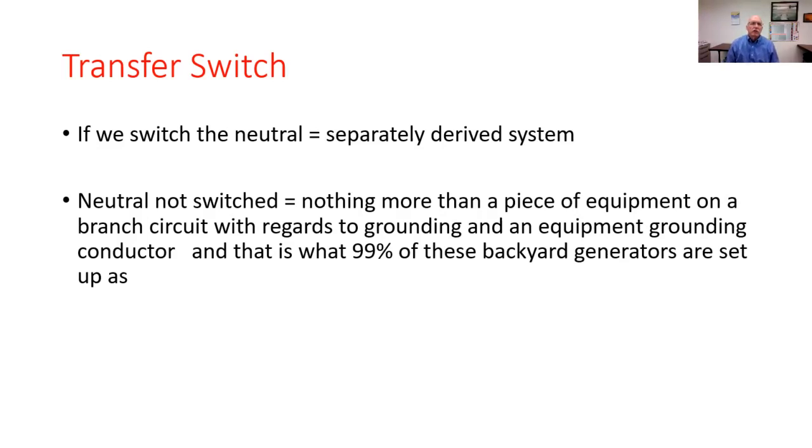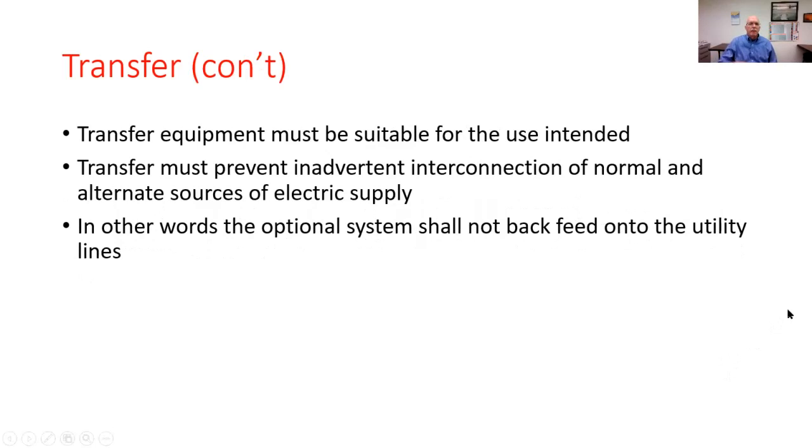And when you don't switch the neutral, it equals nothing more than just a piece of electrical equipment in a branch circuit with regards to the grounding, and the equipment grounding conductor will take care of that. But that's what 99% of these setups are for these backyard generators.